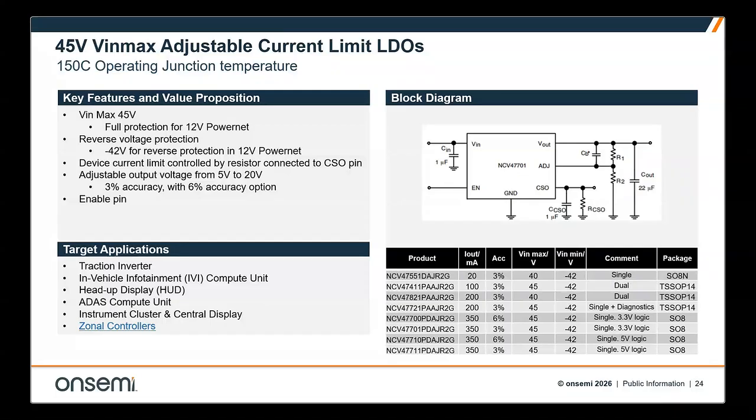Ultra-low 5 microamps quiescent current, accuracy down to 1% at room temperature, and a power good flag with a programmable delay, all stable with just 1 microfarad of ceramic capacitance. That combination makes them ideal for power-hungry compute units, traction inverters, ADAS, in-vehicle infotainment, head-up displays, and so on.